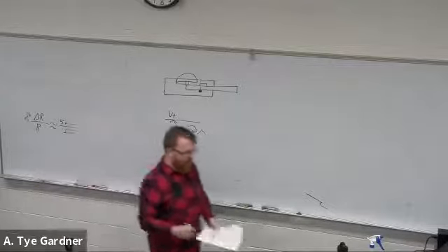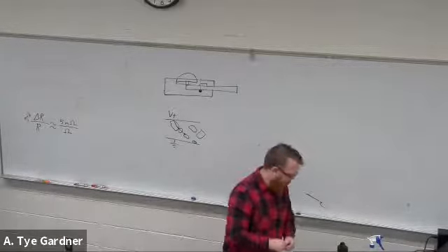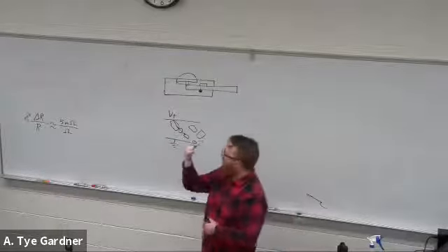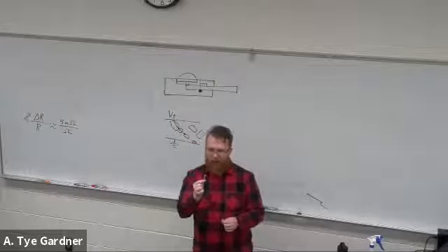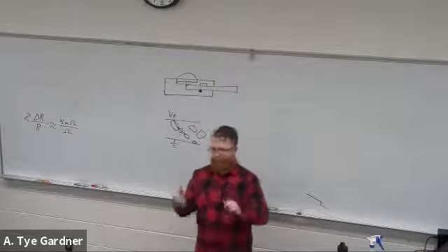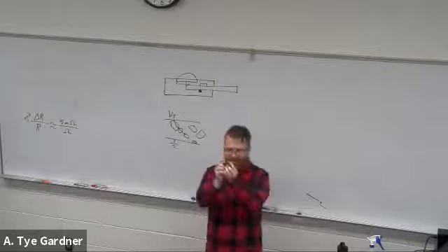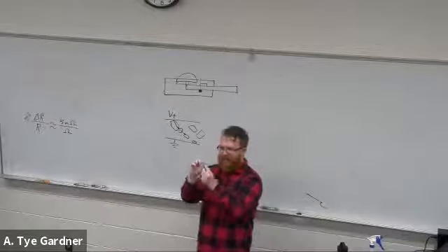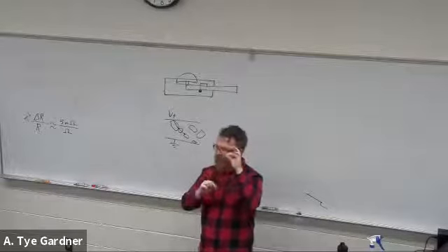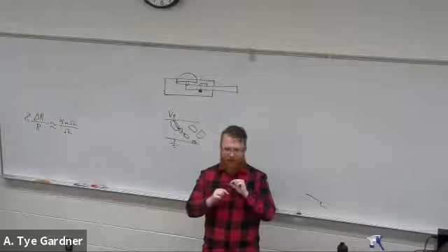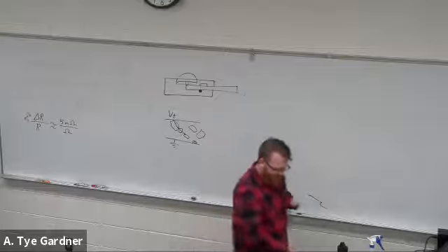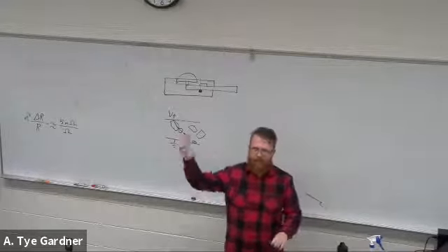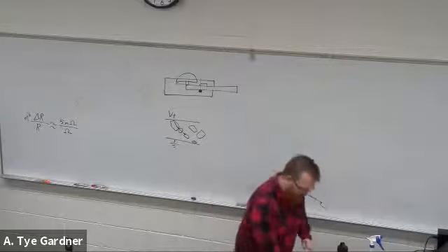So I'm not 100% sure because the data sheet is atrocious, but this little guy, I believe, has a nominal resistance of 300 ohms. So we're going to pick resistors of 300 ohms, right? And we're going to solder up little wires onto this guy, plug him into a bridge circuit, and put little weights on him and measure how things change. Hopefully it works. I haven't done it. I'm going to try and do it before I do the lab, which hopefully I have the weekend to do, but we'll see.